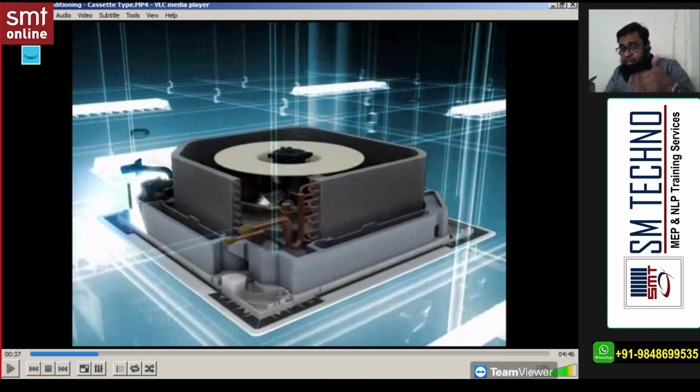So you must take the pipe above the level or at the same level as the unit. If you connect the drain pipe above or at the same level as the unit, it will not drain by gravity, so we require a drain pump. Remember, in all cassette type FCUs, you'll find an inbuilt drain pump to drain the condensed water. I'll show you.